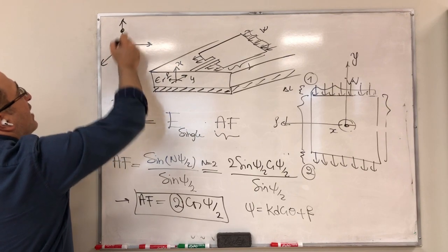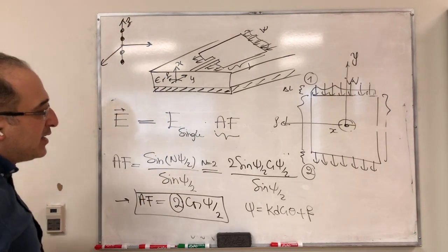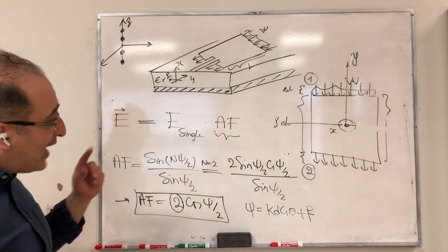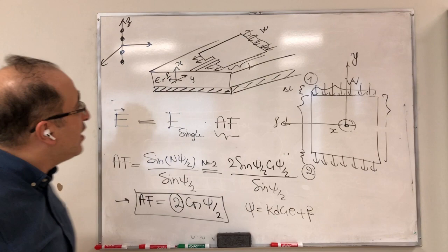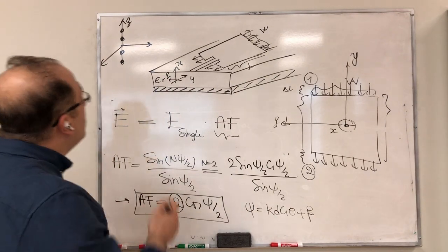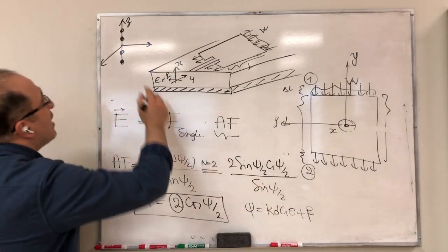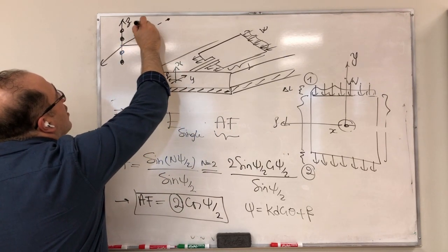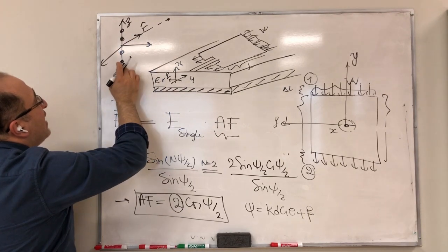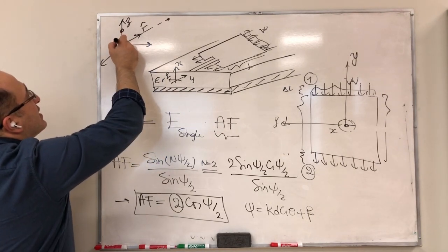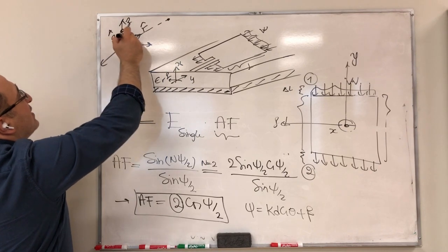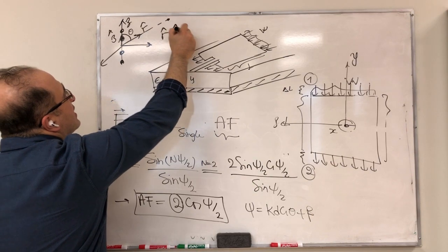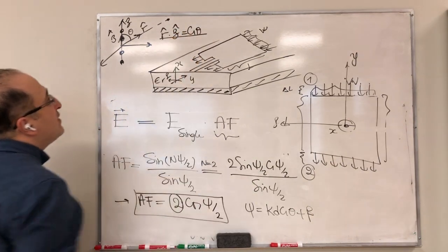That's actually the reason I get cos theta, because if you go through the formulation, you see that this cos theta appears since your observation point is along r hat, and the array elements are along z, so you have a z hat here, and this angle is theta, so r hat dotted with z hat gives you cos theta.